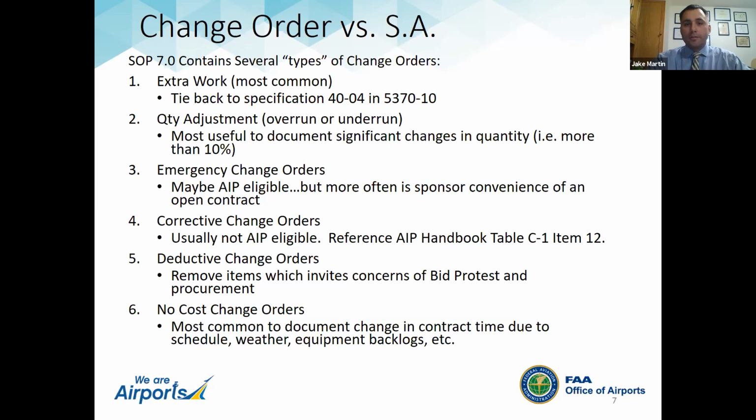Bituminous paving, sometimes the tonnage isn't calculated exactly, and you might originally bid 1,000 tons of bituminous and you come in at 1,100 or 90 tons over the 1,000 or something like that. But of course, crack sealing is a common overrun that comes in 20 or 30% over sometimes because of the challenges with trying to measure the depth and the width of every single crack that's out there. So it's more of a rule of thumb.